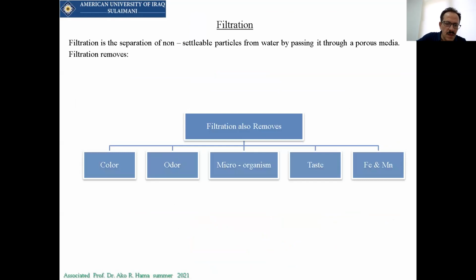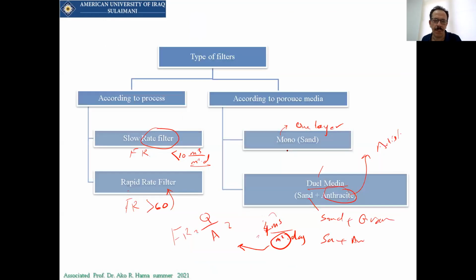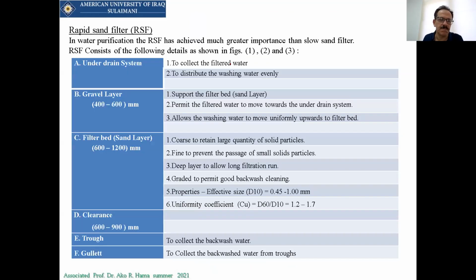Now, I forgot to tell you that we are using the filter to remove the color, the odor, the microorganisms, the taste, and besides that the iron and the manganese. So 99.9% after filtration, the water should stay clean.